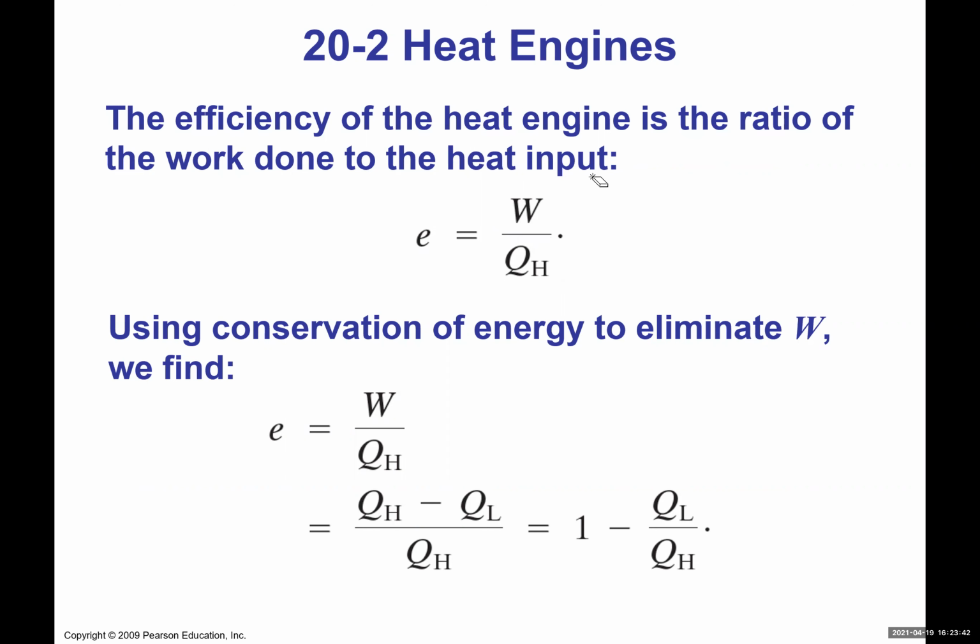So for example, let's say here's a simple heat engine. This is TH, and this is TC, a hot and a cold reservoir. And let's say we put an engine over here that takes some of the energy. Let's say we have QH equal to 100 joules. Out of that, we do useful work of, let's say, 40 joules. That means 60 joules goes into the cold reservoir.